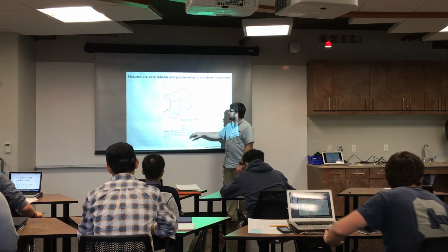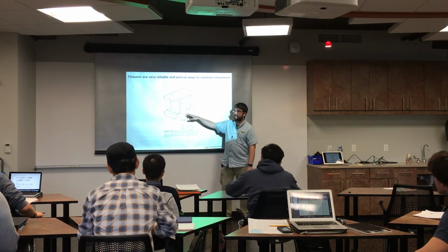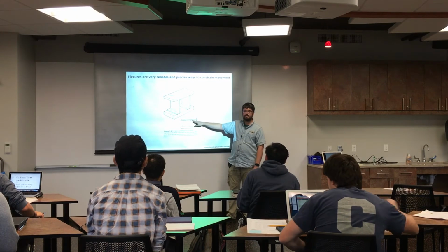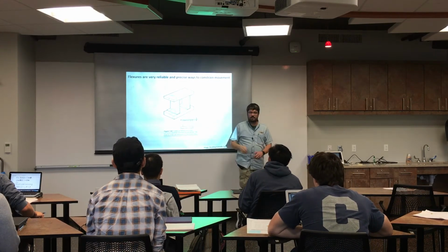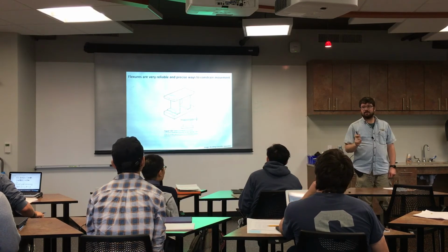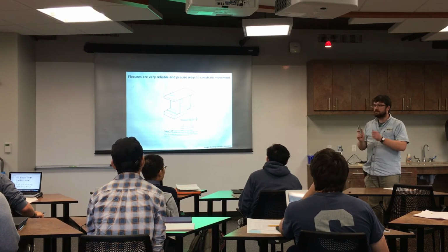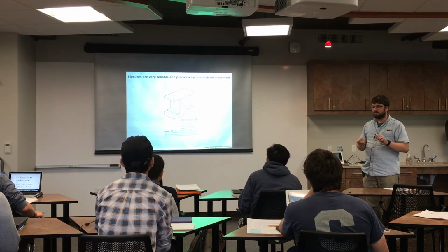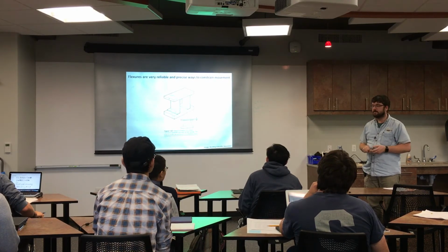There is some error with this kind of flexure design, though, because as we push it and as those bend, we're actually going to go down slightly, right? So you have to decide if you can tolerate that error. But these are really nice, and they're super reliable because there are effectively no moving parts in the sense that nothing is sliding past each other, right? It's just bending of the element.